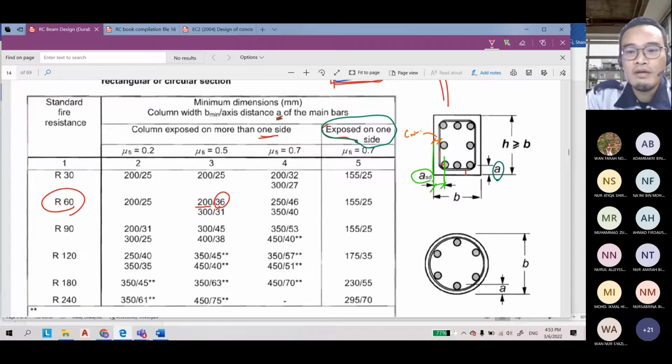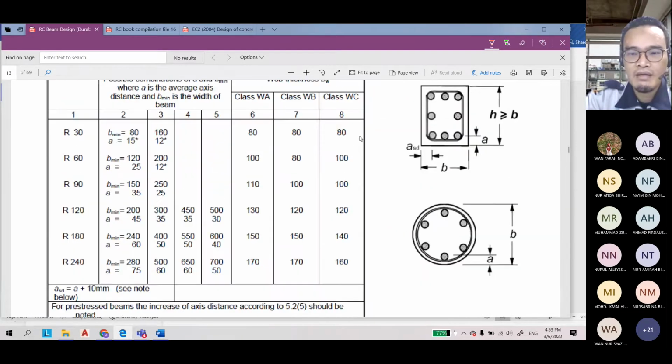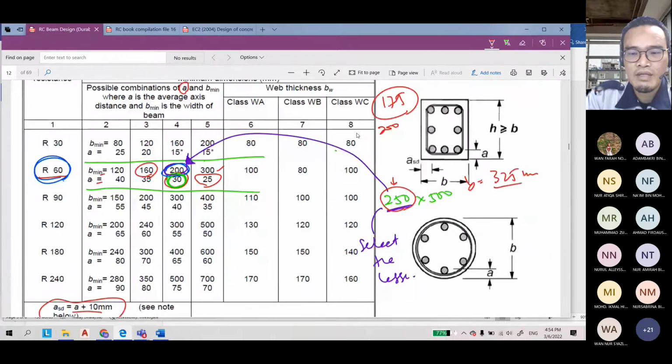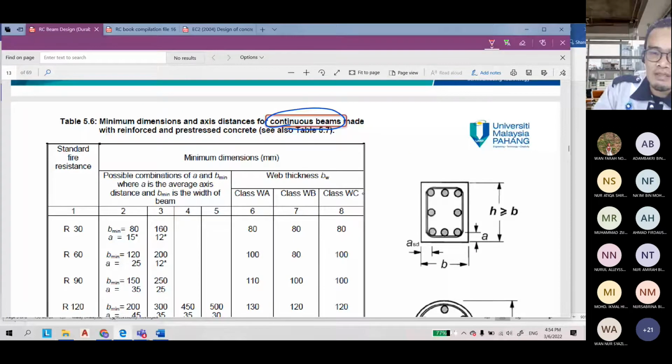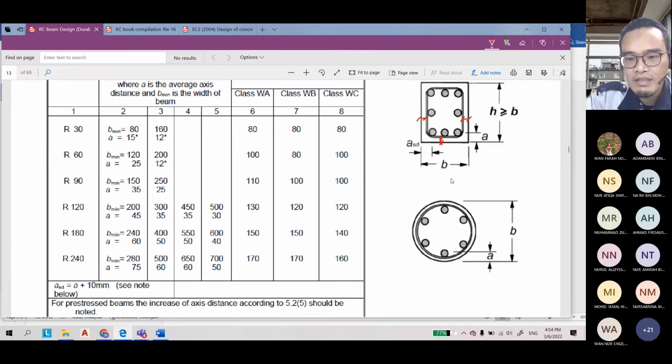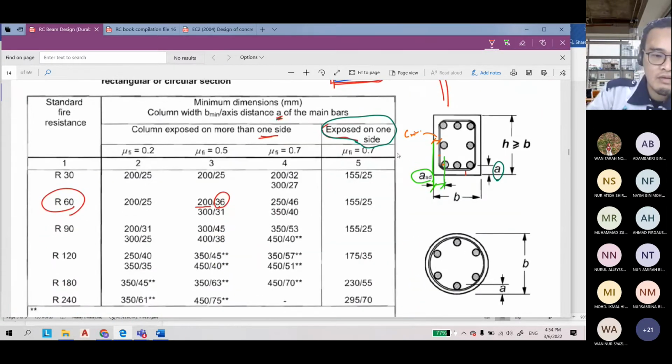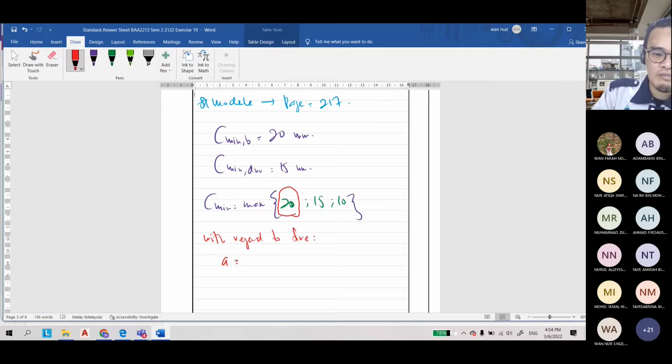the concrete is similar. Let's say for the beam, the bottom cover at the bottom here is not similar to the side cover. Maybe bottom cover is 30 and side cover is 25, let's say. However, for the column the cover is similar all around. This example we don't know the value of this one, so you can assume inside your answer.